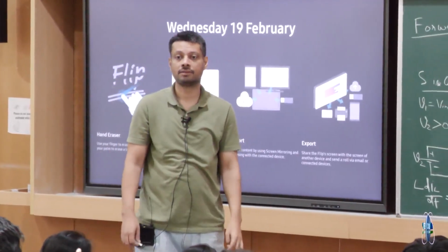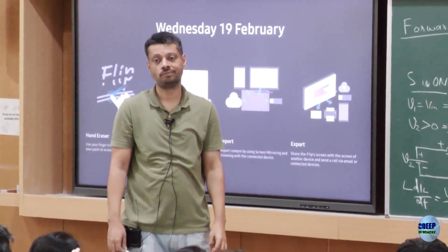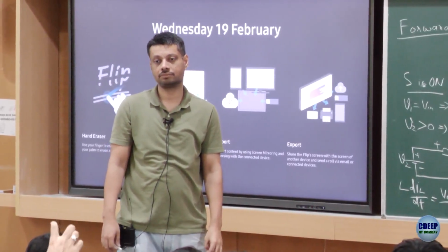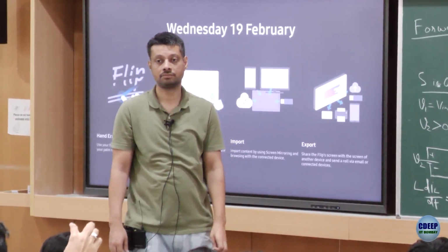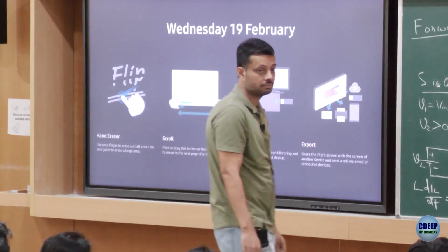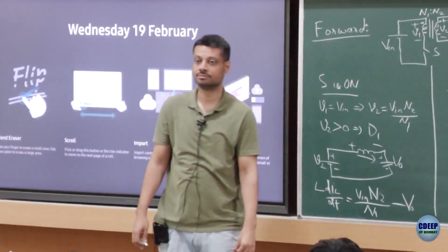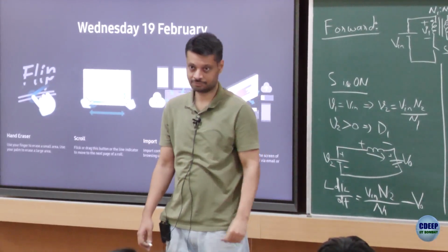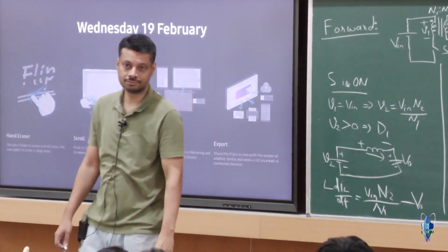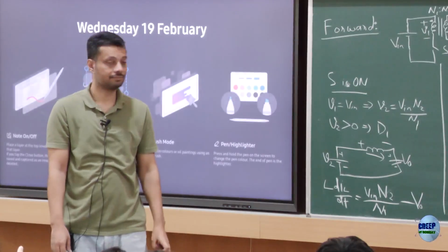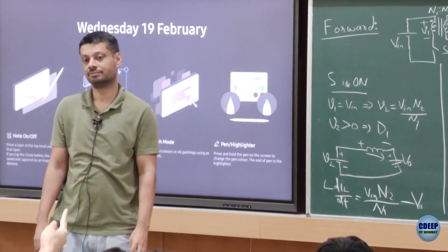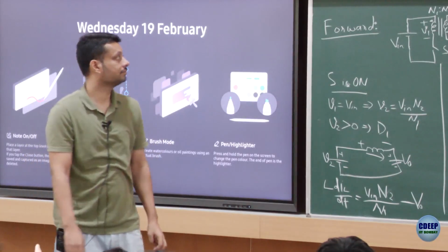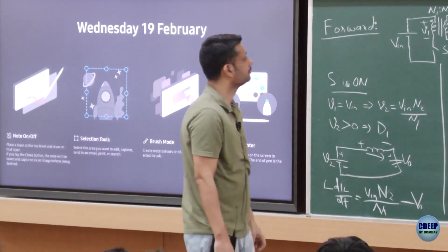If we have a practical transformer, on the left side there will be that magnetizing inductance. So it will also have some current when S is on. When we turn the switch off, that current would still try to keep flowing. So that would appear on the V2 side. But if we keep the diode, it prevents that from interfering.